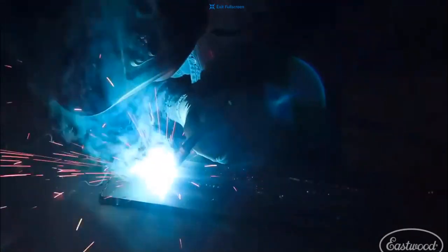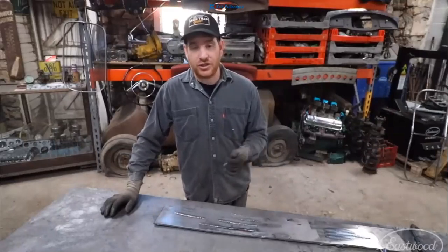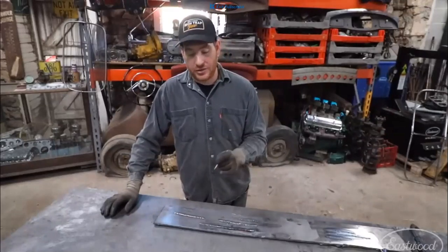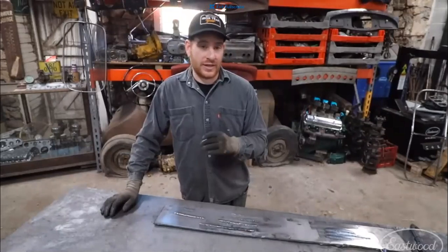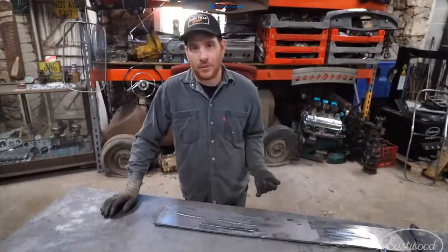If it's something that's thinner, you may get a lot of warping in the panel, it may heat up, and your weld will get extremely large. You need to find a happy medium where you're moving across the panel, pushing the weld as you go, making sure that you're kind of circling back into the weld to get nice overlap so there's no pinholes or gaps in the weld, but you're also not burning through.